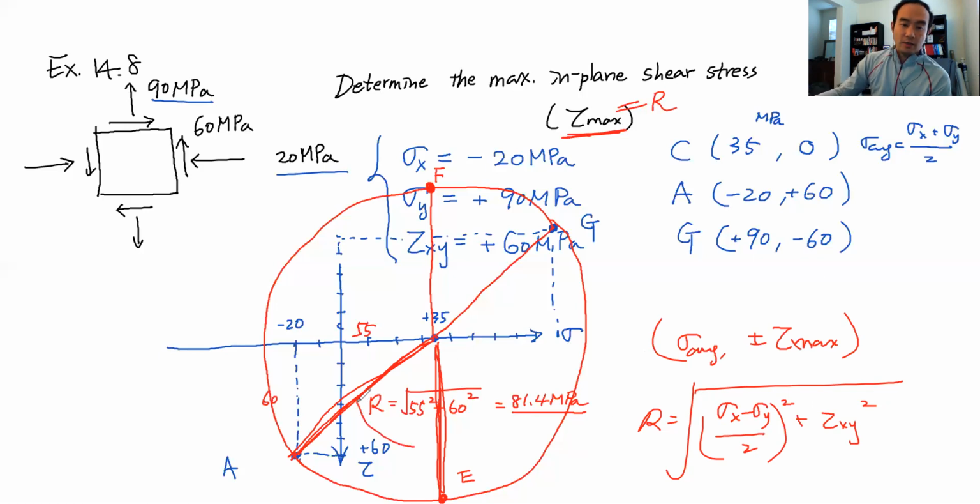when you estimate this angle in the Mohr circle, I said it is going to be twice the actual angle in the real plane, right? So this angle is going to be equal to 2 times theta s. So theta s is the angle from this current condition. I changed the angle in the counterclockwise direction. So we have to go in the counterclockwise direction as well with this much. The angle in the Mohr circle is going to be twice theta s.